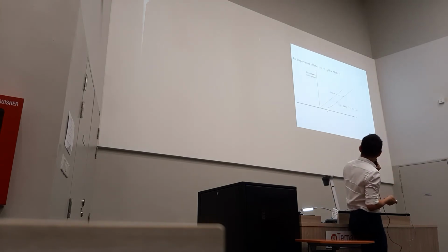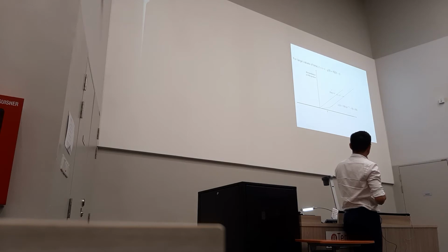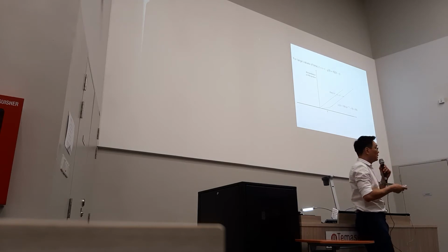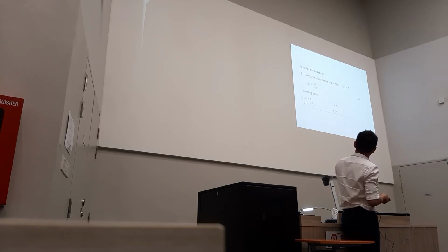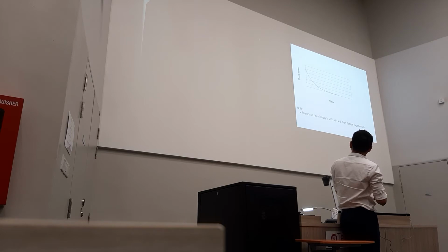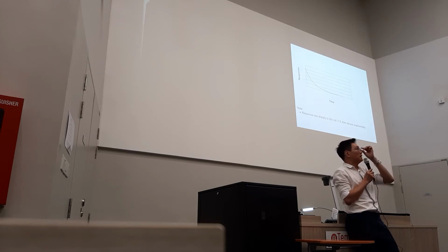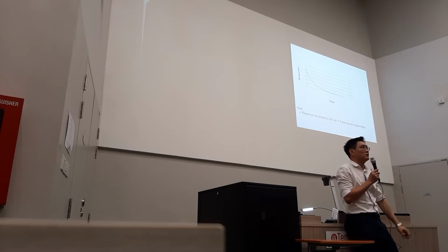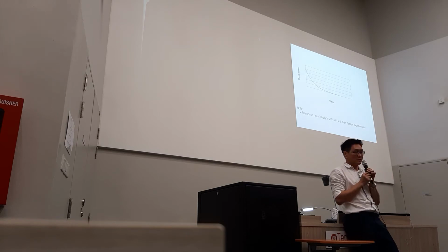Of course, we also have the ramp. For the ramp we refer to this graph, which is the response when the disturbance equals the ramp. Of course, the impulse looks like this. It's actually a negative exponential. These are the 4 important disturbances that we put into the transfer function. We will see all these 4 different types of behavior, okay?